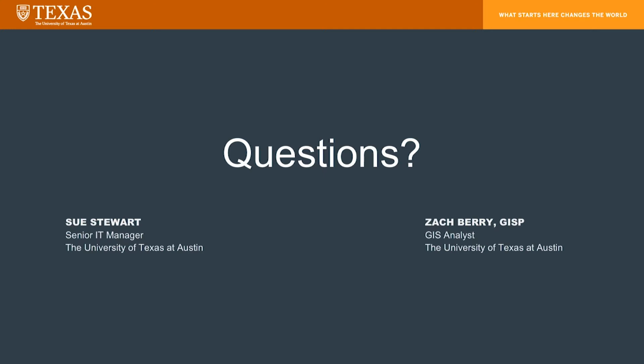Any more questions? How do you designate the accuracy of the utility? What system are you using? Are you talking about in terms of field surveying method? We're using Trimble total stations. No, I mean for the existing utilities, a system like A, B, or C. It's D, mostly D. Everything that came from the original CADs is all D to us.